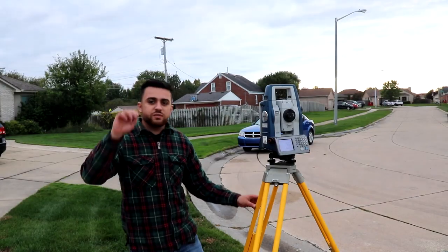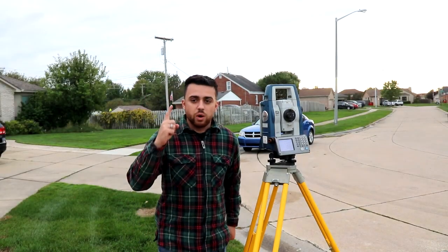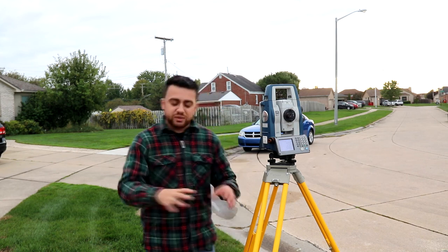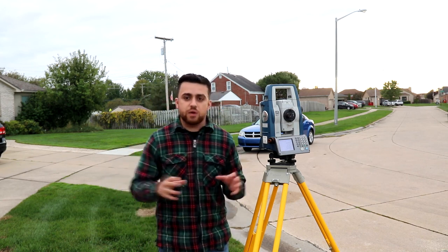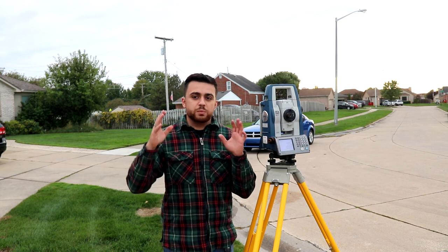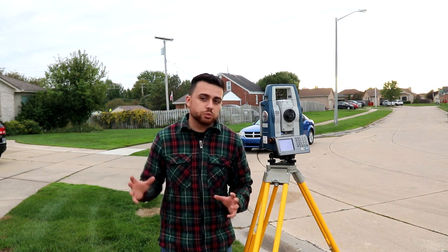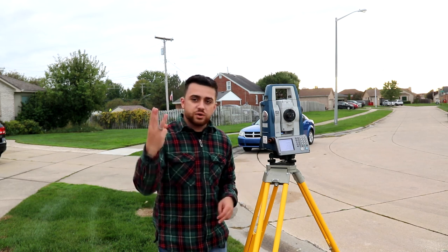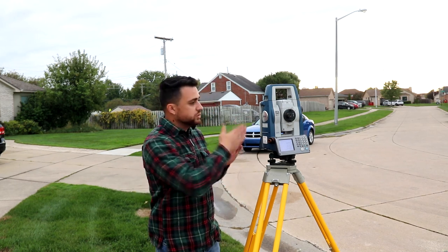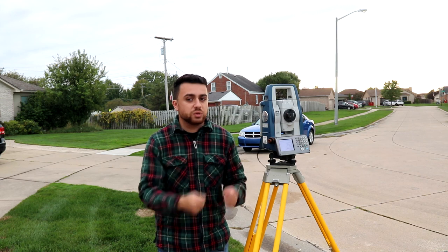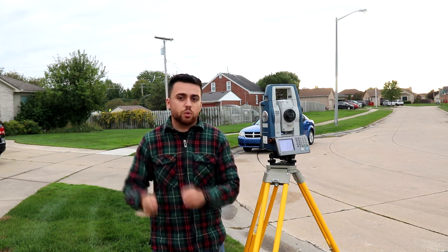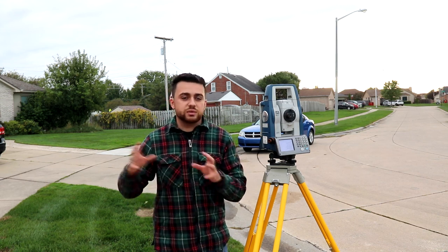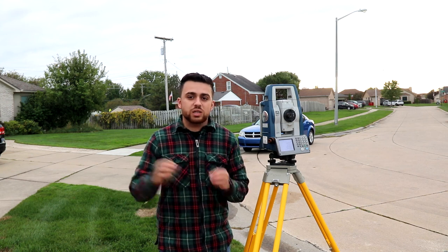But when it comes to topos, we're going to be in land that we're surveying. Topographic surveying depends on three things. One, establishing a control network so that we can figure out where we're located in our project. Second, we need to be able to backsite a referenced control point in order to establish a scale for our project. And third, we will then be turning the angle several times and taking several foresights and measuring different points and coding them with different descriptions so that we know exactly what we're sighting.